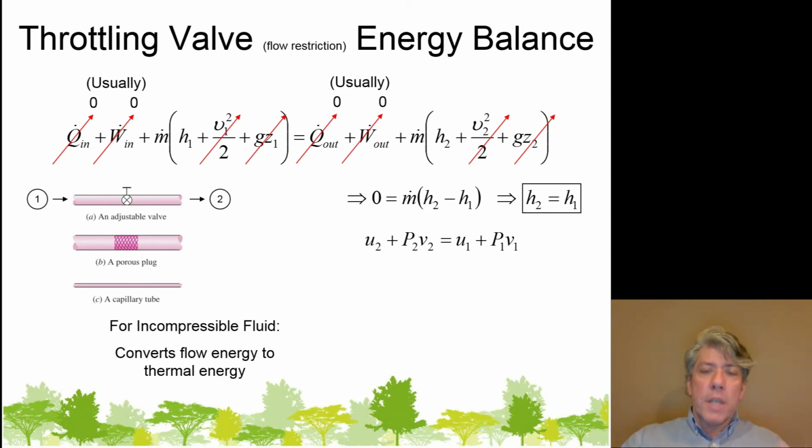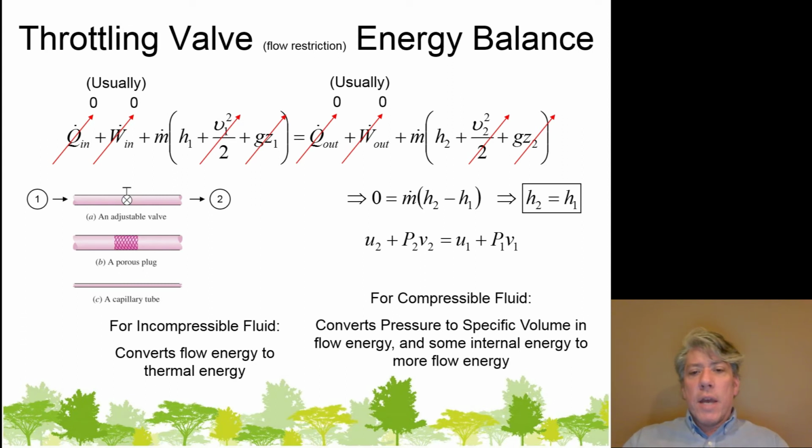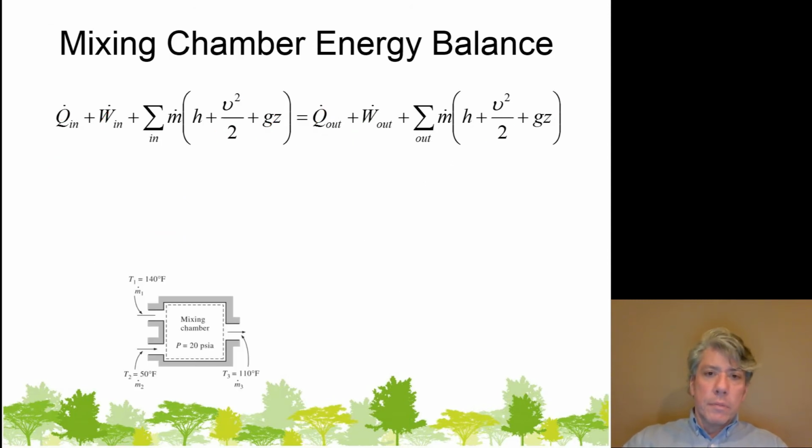So for an incompressible fluid, where the fluid does not evaporate, where there's no evaporation, then there's just a conversion from flow energy to thermal energy. On the other hand, if you have a compressible fluid, you've got to figure out what will happen. But if you have a liquid that's going to boil off, a phase change, then typically, depending on the property of the particular fluid, a certain amount of thermal energy will be converted to flow energy.